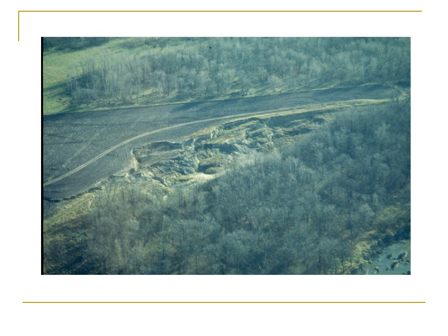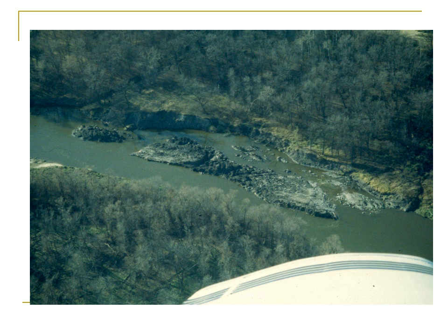Here's a closer view of the scarp, or the upper part of the slope. It wasn't a very steep slope, but here's the scarp showing the farthest back this rotational failure ever got. And this is a close-up view of the toe of the slide area where soil was emerging after rotation up in the center of the river, causing it to dam up and threatening structures both upstream and downstream.